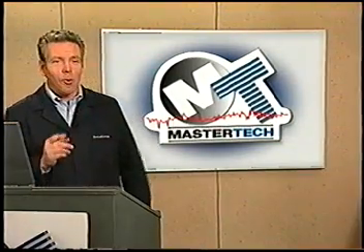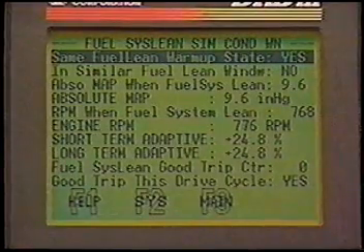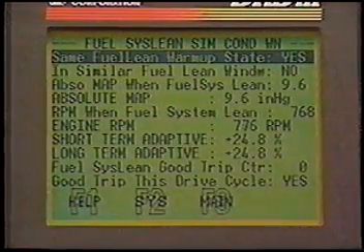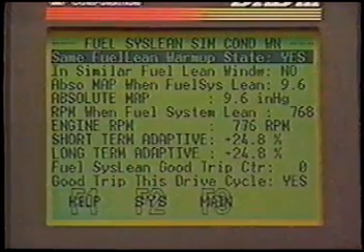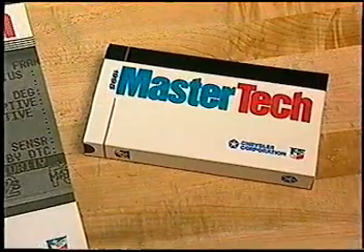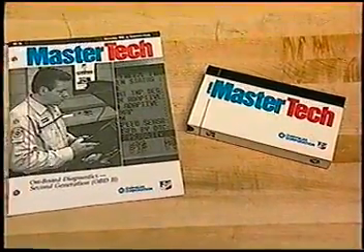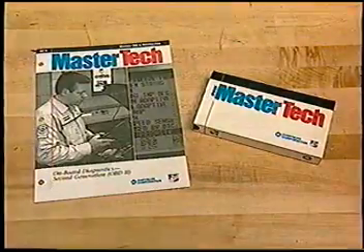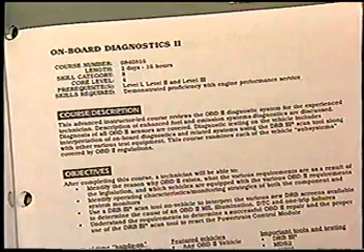operation. One last aspect of onboard diagnostics that you may already be familiar with is the similar conditions window. This is a set of parameters for vehicle conditions that must be met for the monitor to retest after the first fault. The similar conditions window only applies to fuel system and misfire monitors. For more information about the similar conditions window, refer to the November 1995 MasterTech program. You can also refer to applicable training course information.